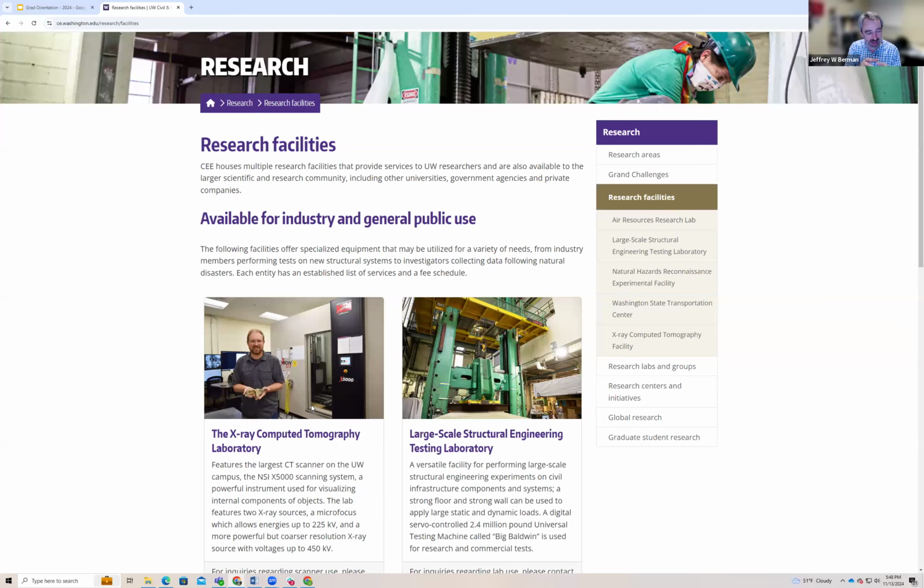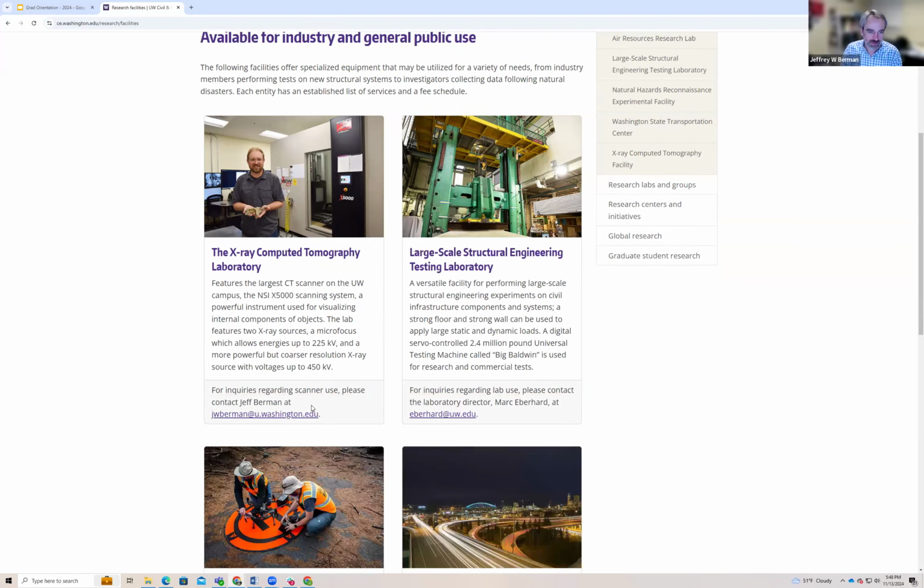We can see inside, see reinforcing steel inside large sections of concrete. And so what we often do is pull out the failed section of a large-scale test and then scan it in the CT scanner to investigate the failure modes in more detail.